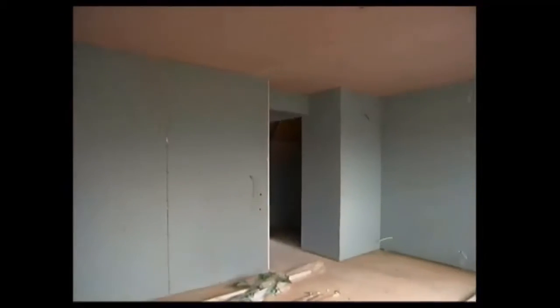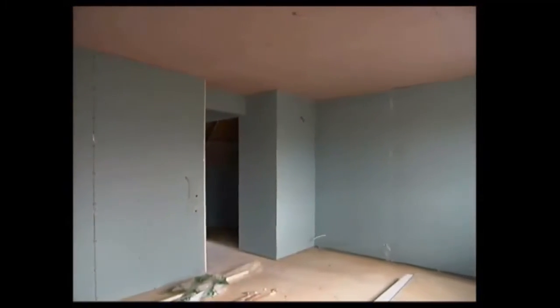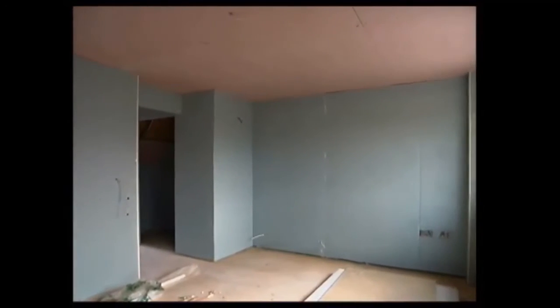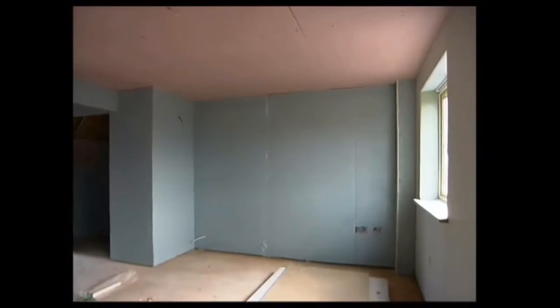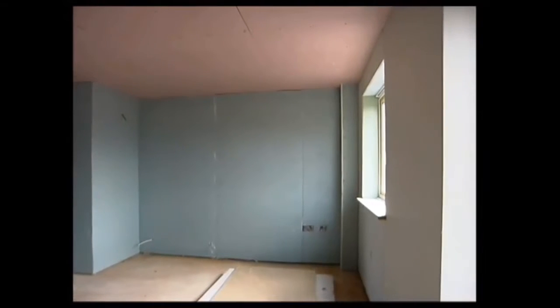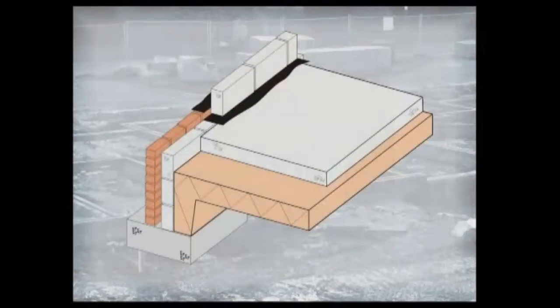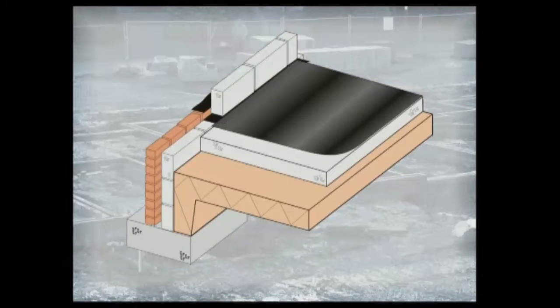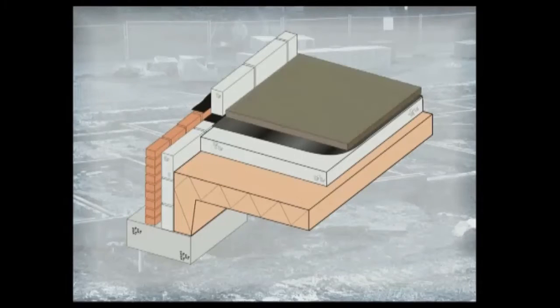Laying moisture-sensitive floor finishes cannot take place until the screed and slab are dry. When the DPM is laid below the slab, this can take several months. The problem can be partly overcome by separating the screed and slab with the DPM. The damp slab no longer affects the screed, which can then dry quite quickly. This sandwich membrane can be formed from polythene or a number of liquid solutions.